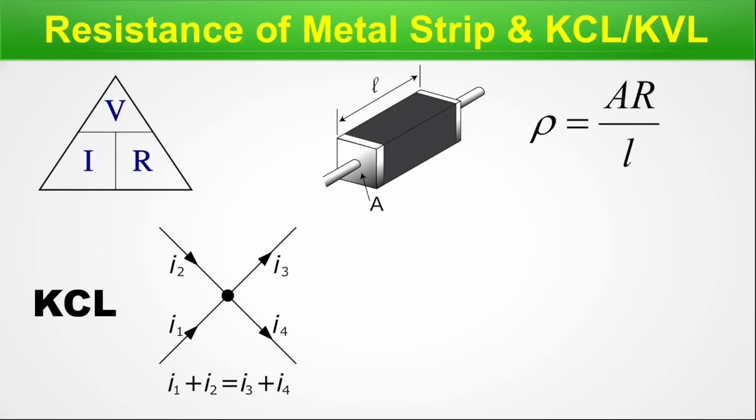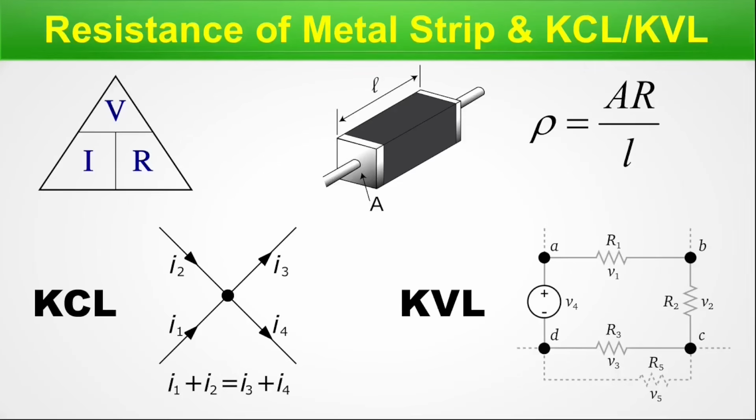All these concepts are very much important in the IR-Drop analysis, and we are going to go further in upcoming slides. The KVL, that is Kirchhoff's voltage law, we can also imagine from this circuit here. You can see the sum of all voltage drops equals the supply. So I have touched on the basic physics in this particular slide so that you can correlate it with a finer-grained concept of IR-Drop analysis in upcoming slides. So we are done with this particular slide.